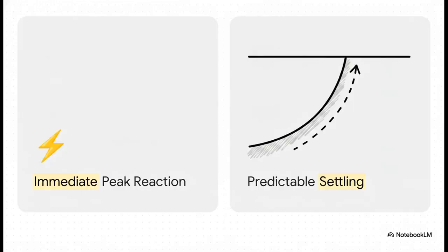It reacts instantly, and then gently settles into that exponential curve, inching toward its final value without ever swinging past the target. In a true first-order system, you literally never have to worry about overshoot unless the controller itself is forcing it to happen. The natural physical response is just a clean, steady climb right to the finish line.